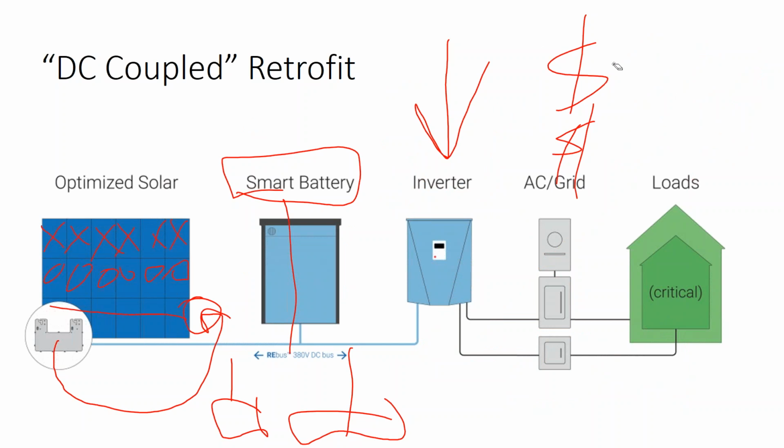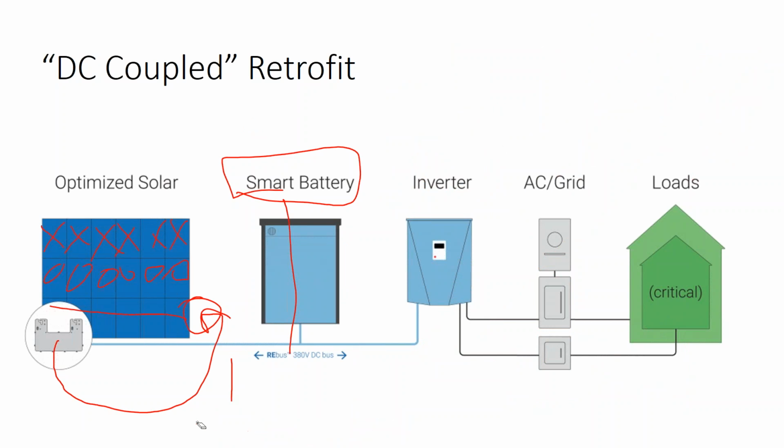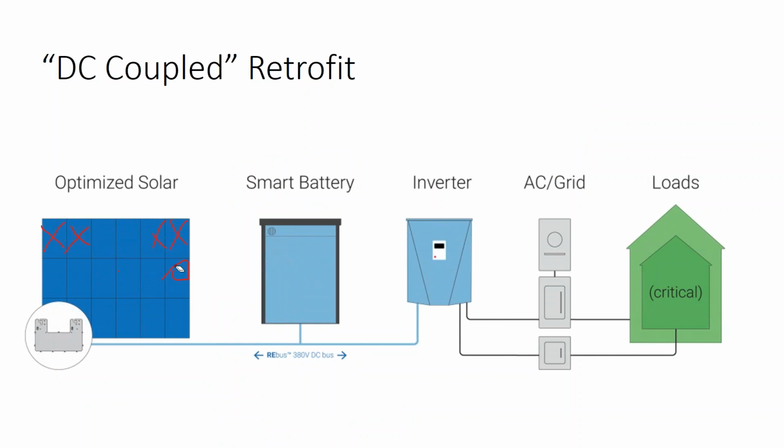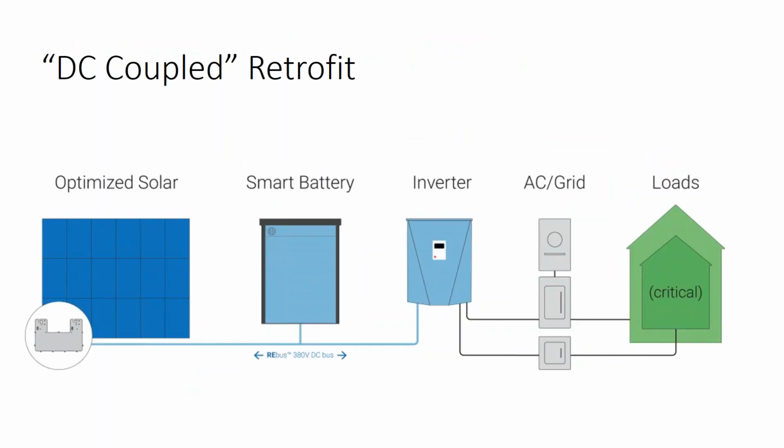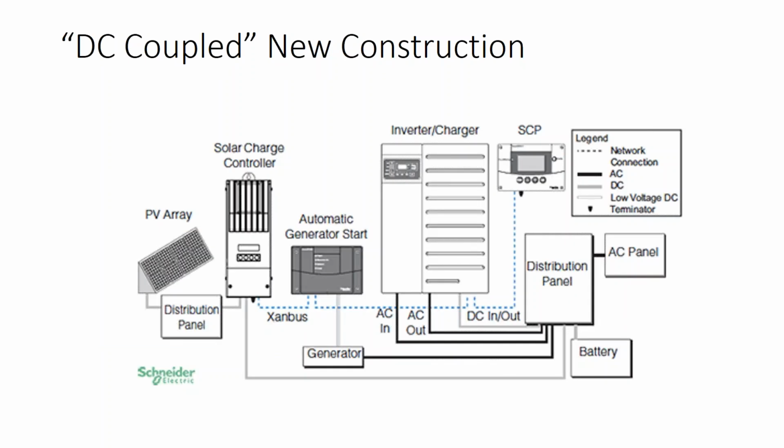So when you get into product selection, there are some battery inverters on the market where you can do the solar array today and add the battery tomorrow. But your traditional battery inverters like Schneider or Outback or SMA, kind of the big names in batteries at this time as far as the inverters go, they're all designed for only one battery chemistry.